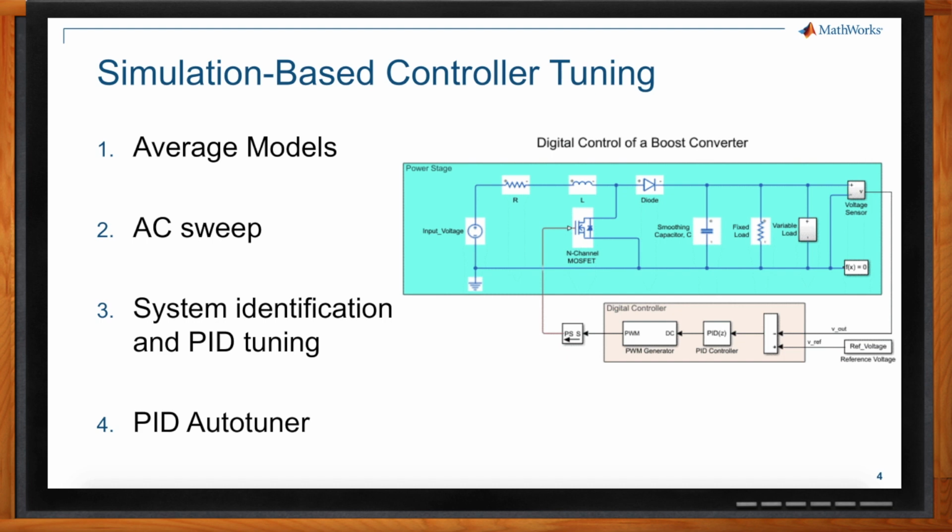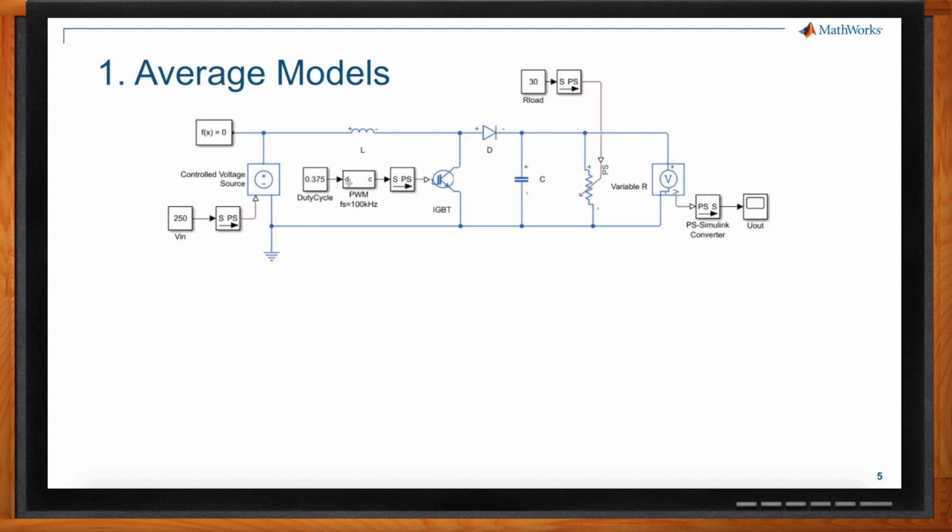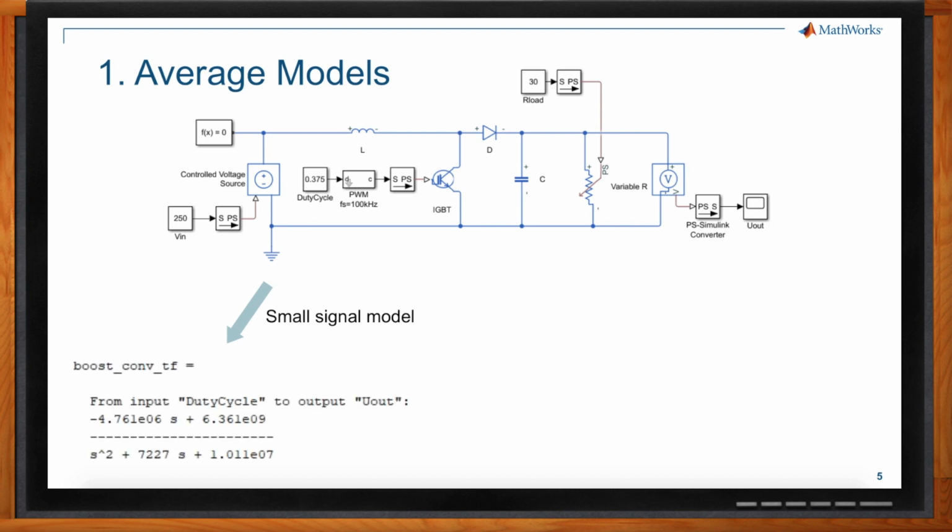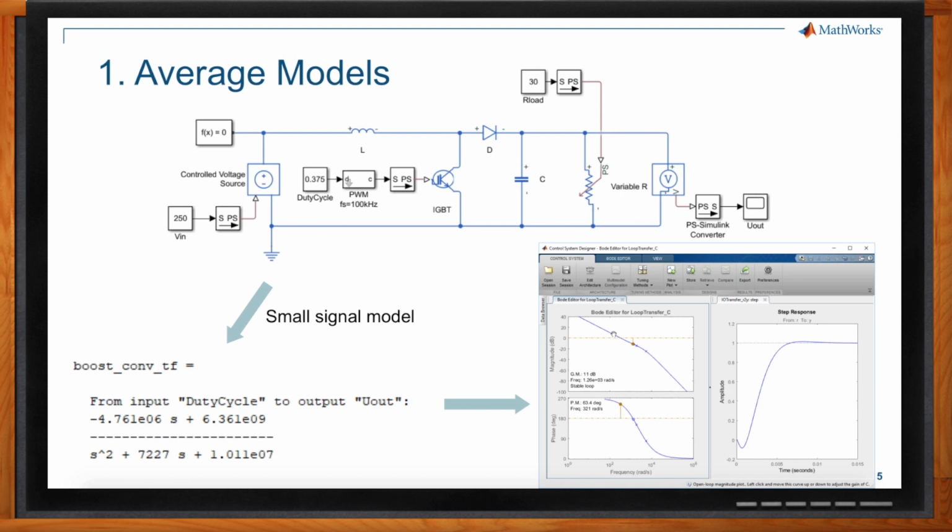So what that means in the context of power electronic systems is that in those systems we have components such as an IGBT that you see in the picture here, or diodes. For us control system designers, those are essentially switches, so they can be on or off. And depending on the position of the switch, on or off, the system dynamics is changing. And so one thing we could do is to try to approximate this generally nonlinear dynamics with a linear system.